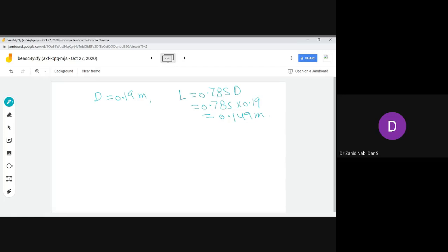So for the number of stator slots, we have to calculate the turns per phase. First of all, the number of conductors, that is Zs. I told you if it is a three phase machine, it would be 6 times Ts. Okay, 6 times turns per phase. For a single phase, Zs is equal to twice T phase. So first of all, we have to calculate this T phase.